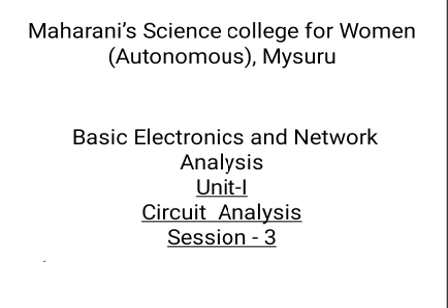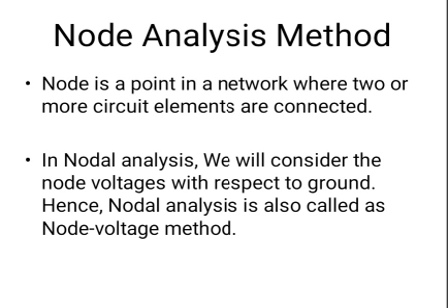First, we must know the definition of the node. A node is a point in a network where two or more elements are connected. In nodal analysis, we will consider the node voltages with respect to ground. Hence, nodal analysis is also called the node voltage method.